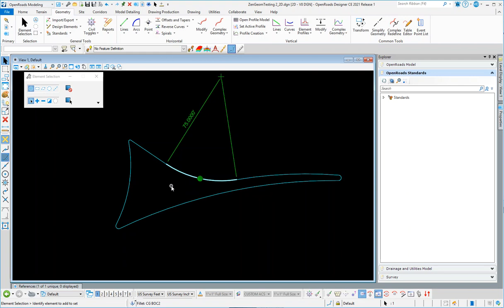So if you really want to make it more intelligent, I would bring it all in like this, in these pieces, and then I would delete out the curves and replace the curves in there by trimming with the radius. So now you could change it back to 91, and it will automatically be trimming. So if you have the option here to modify this, it's going to keep this thing trimmed. That's where you get a lot stronger editing capability. I'm just going to undo that. So this should be back to 91.